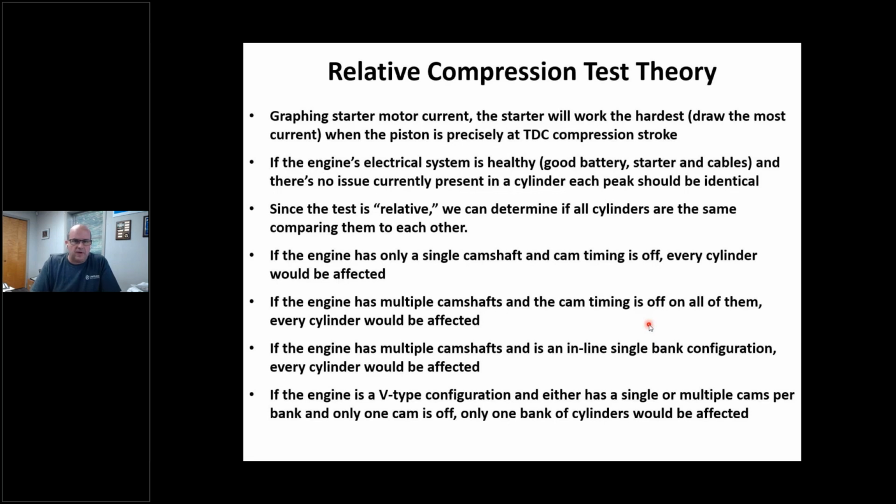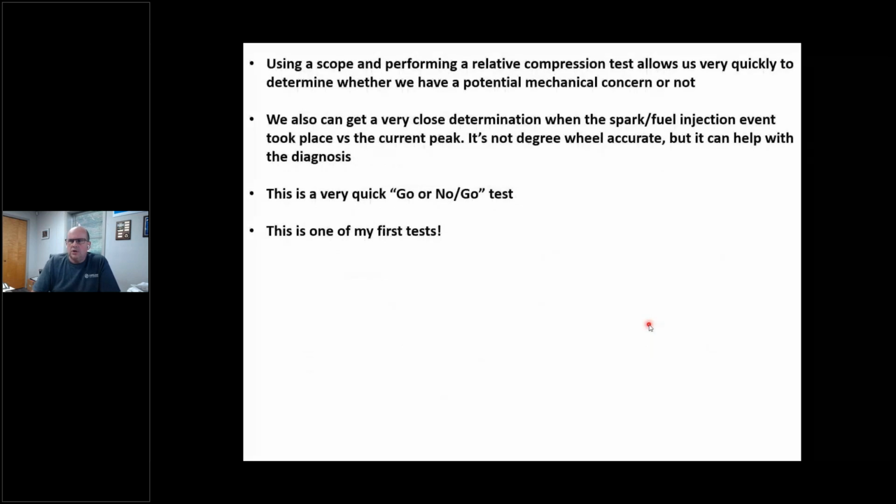I've got case studies. I'm sure if you guys have watched me before, you've seen me do case studies on Nissans and some other vehicles where the timing wasn't correct, and you could see it on starter current, which is pretty interesting. If you've got misfires, for instance, on one bank, one of the things I like to do right out of the gate is this relative compression test. I'm not talking cranking vacuum today on diesel, but it's a very good test. Using a scope, I can perform this test quick. It's non-intrusive. I'm taking a current clamp around a battery cable, and I'm going to trigger off an event. We always trigger off a combustion event, such as a fuel injector of a diesel engine or a spark event of a gasoline engine.